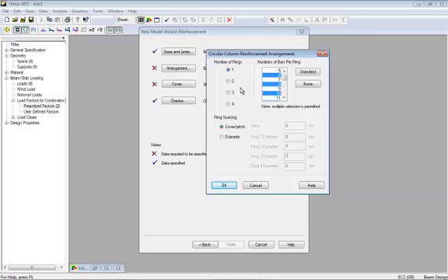With the bar sizes and the number of arrangements here, AdSec will look at each of the possible combinations of the bars and the arrangements, check them all for detailing requirements, compliance, and those that pass will then go on to the design check.